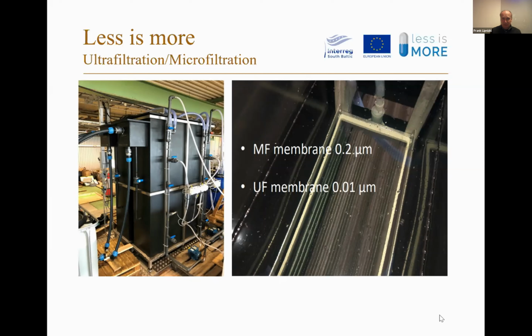We used a microfiltration membrane, in this case a 0.2 micron membrane from Alfa Laval, and also an ultrafiltration membrane with a 0.01 micron pore size, which is equivalent to about 10 kilodalton in molecular weight cutoff. And that was the UFX membrane we used there. It's a hydrophilized polysulfone membrane. So with these two membranes, we did our direct membrane filtration.